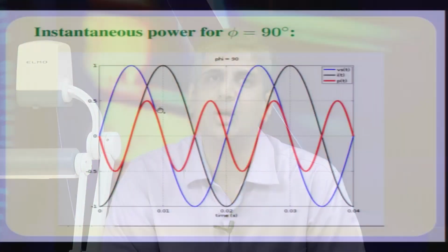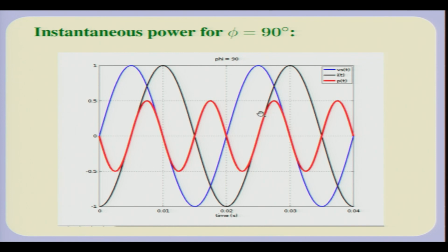But the important thing to be noted here is, in this case as in the previous cases, the magnitude of the current is still the same. So, what it means is that you have these elements which are not dissipating any real power, but still nonetheless drawing power from the source. That is a very interesting thing, that in AC circuits you may have to live with such components which draw current from the source, but do not dissipate any power on the average. That is an important point in steady state, again please remember.